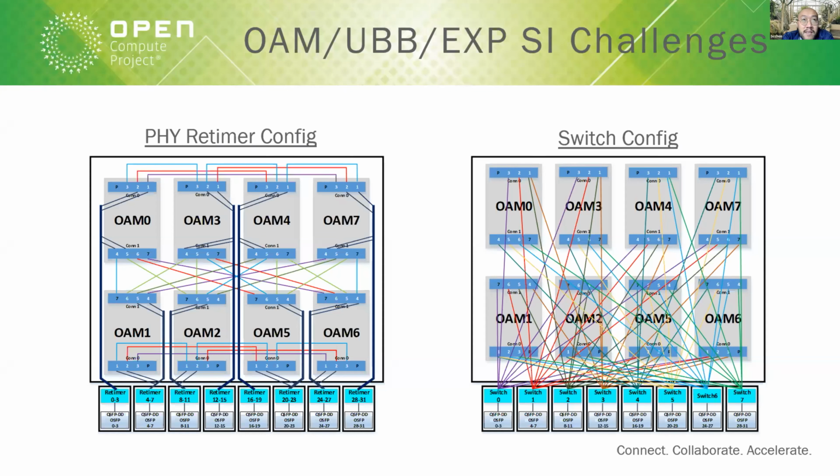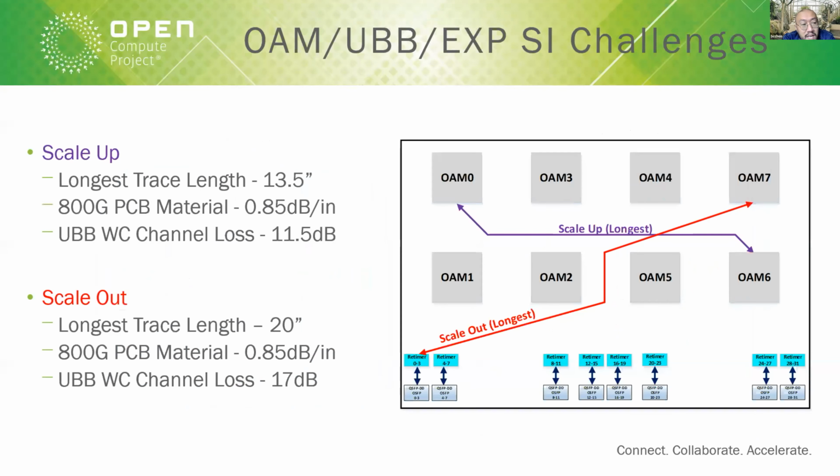simulation, and compliance with the COM, by IEEE 802.3ck, right? Because that's the equivalent to 112G LR. Next slide, please, Son. So we did two examples: one of the longest trace for scale up, the other is the scale out longest trace. As in our example, we did an actual layout. We found out that the longest trace on the scale up, which is OEM to OEM, will wind up at 13.5 inches. Then we use the 800G, the class 8 material.